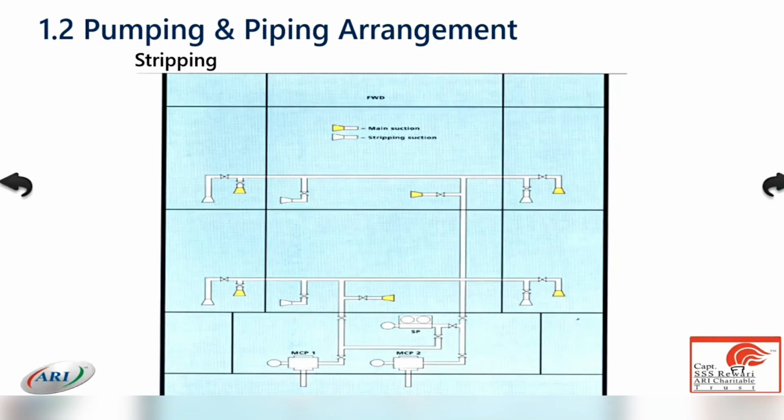The outturn figure of the ship has literally improved by changes in the construction and having a proper stripping system installed. Many ships have 2 eductors instead of 1. Very effective. So these days operation on tankers is quite simple compared to what we used to have earlier when we had a single skin vessel. All the longitudinals, transverses, all the stiffening was in the cargo tanks. It used to be very difficult to strip the tanks.